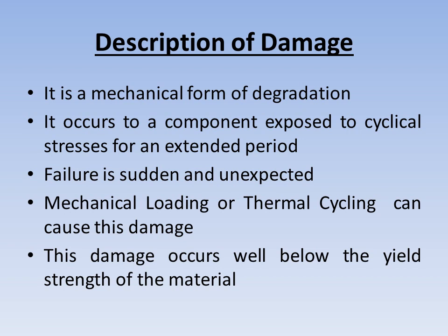The damage occurs well below the yield strength of the material. Well below the yield strength. Normally, a material fails when it is loaded above the yield strength. But here it fails below the yield strength when fatigue happens. That is why the damage is unpredictable.